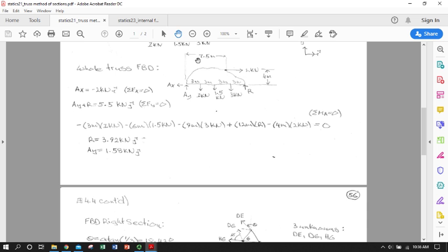So I have included only the dimensions that I need to put this in static equilibrium and calculate moments and forces. So some of the forces in the X, I know that A sub x is going to have to be pointing in the direction given with 2 kilonewtons to balance the applied load. The sum of the forces in the Y says that A sub y plus R minus all of the applied vertical loads is going to have to be equal to 0.